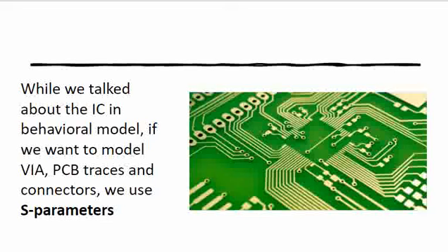So the S parameter model includes the losses associated and the performance associated parameters of wires or the traces on the PCB or any passive structures that are there on the PCB are specified by the S parameter models.